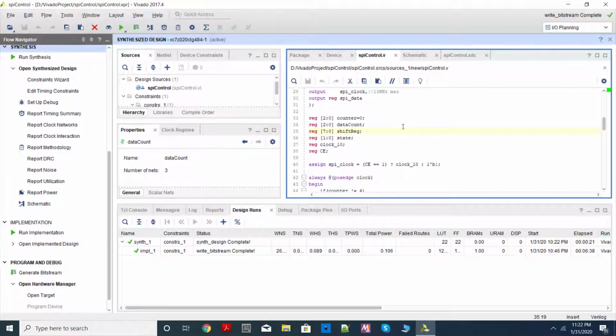But during debugging, we are not worried about performance. We are worried about functional correctness. So at this time, what I want to tell it is don't change my signal name. To do that, we use something called attributes. In Verilog you may not have seen attributes before.